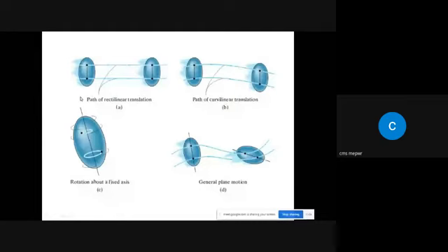So over here we have a rigid body. This rigid body is moving from one place to another. So in this case, let's consider any 2 points. They move from here till this point, and they are following a straight path. So this is basically rectilinear translation. And now in this case, these two points are following some identical curved path. So this is basically curvilinear translation.